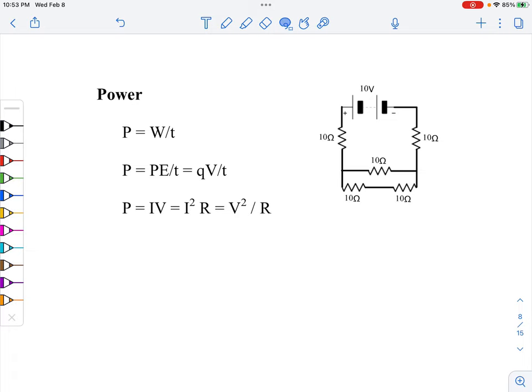When we build, those big cables are made out of aluminum. Aluminum is chosen over copper. The reason, number one, it's cheaper. Typically copper is more expensive. But maybe even more important, it's lighter. A meter of aluminum at some thickness is lighter than a meter of copper. It's less dense, I guess is the right way to say it.